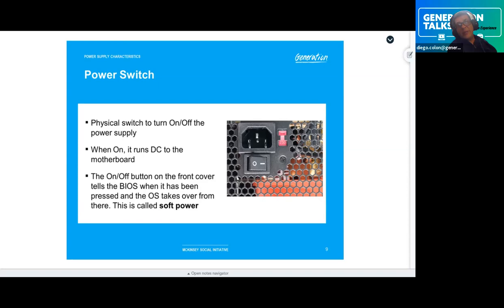Okay, in the physical switch, now we have a much clearer picture than the other ones. We'll see here the actual little doohickey where we come in, the black cable that everybody's used to seeing with the three-prong female connector. This one on this side is the actual male connector, which we can connect directly to the wall. The red switch on the right is the dip switch to switch from 230 to 115 that they taught us earlier, right? Because it flows on average about 115, anywhere between 110 and 120. And then here they have the 230. Again, the little kill switch there is the main one to turn off completely.